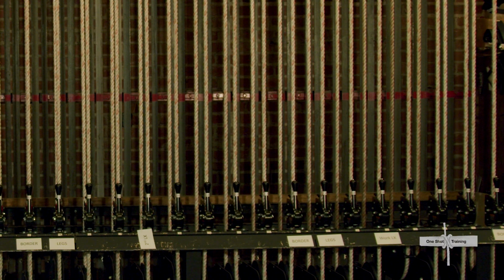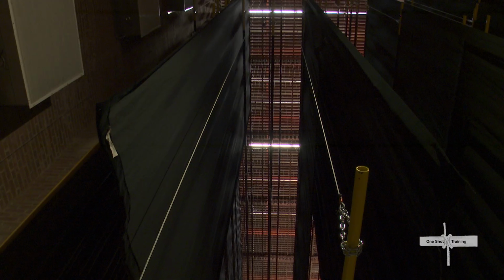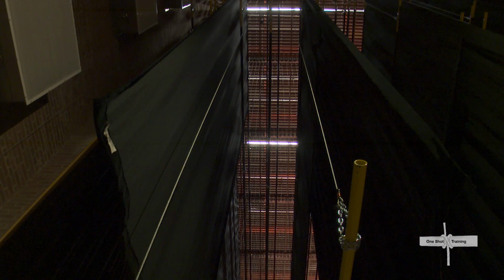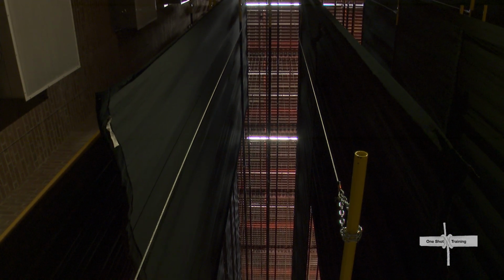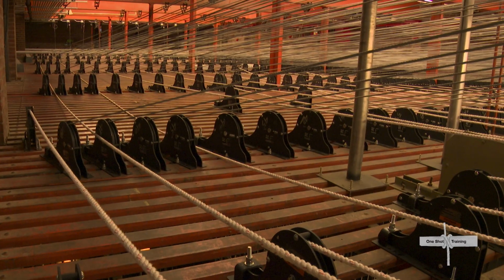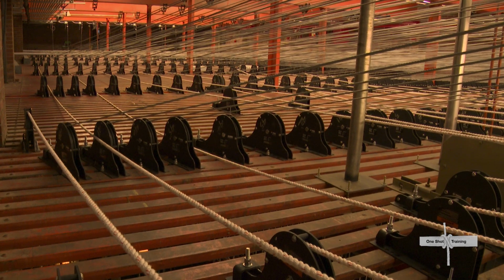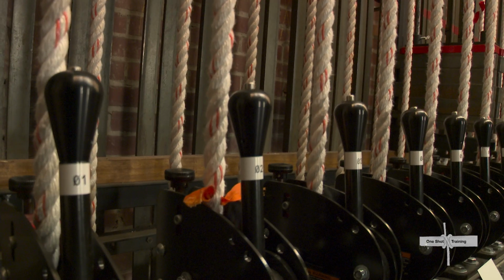A more common, more modern fly system is a single purchase counterweight system. Loads are attached to a batten, which is held by several lift lines of wire that typically are 8 to 12 feet apart. Each lift line goes up overhead through its respective loft block, then through a head block and down to a counterweight arbor.